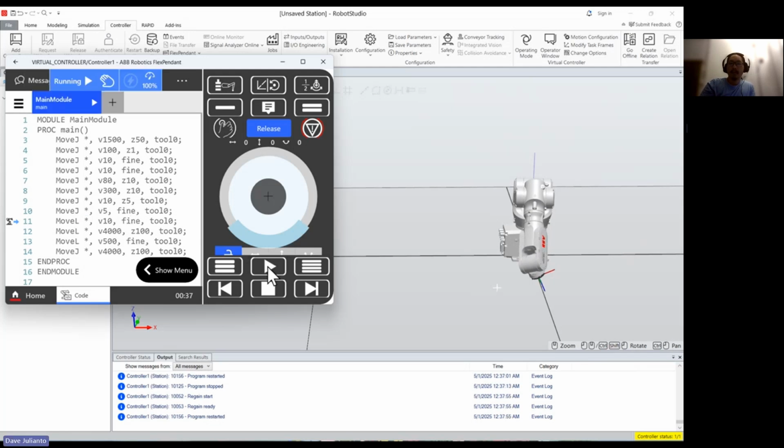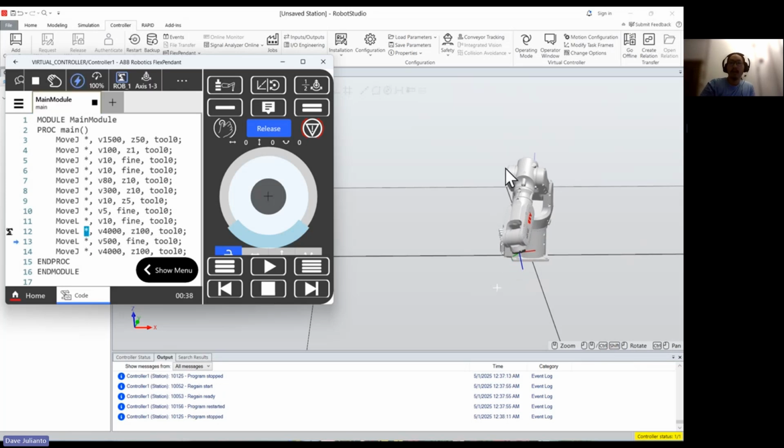And it's done slowly. This is a linear move because there's only one axis that's moving. And here, we're trying to move the robot to another defined point, but instead of moving it with move J, we tried it with move L. And in this case, it moved just fine and there's no error message. There's two more L moves, right?